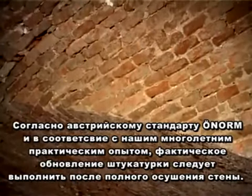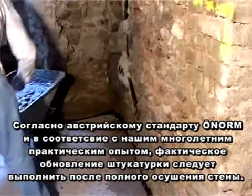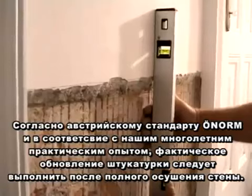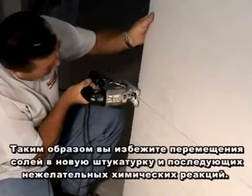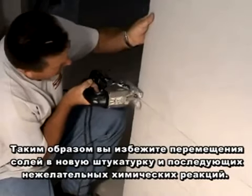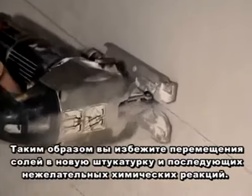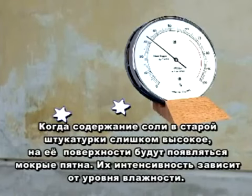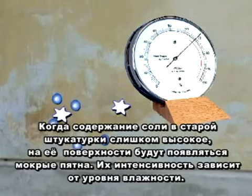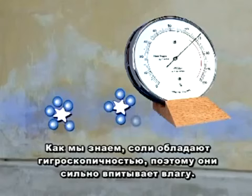According to the ÖNorm, the Austrian standard, and according to our long years of practical experience, the actual plaster renovation should be performed only after the wall has been dried. One thus avoids migration of the salts into the new plaster and a consequent undesirable chemical reaction. When the salt content of the old plaster is too high, moisture spots will appear on the surface. Their intensity depends on the level of humidity. As we know, salts have hygroscopic properties in that they strongly attract moisture.